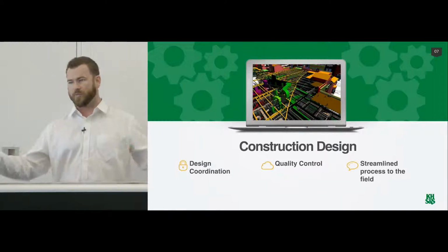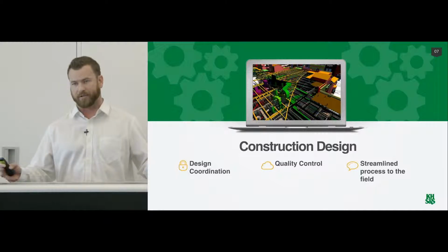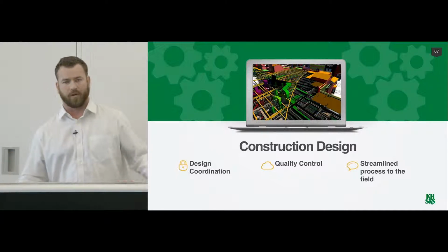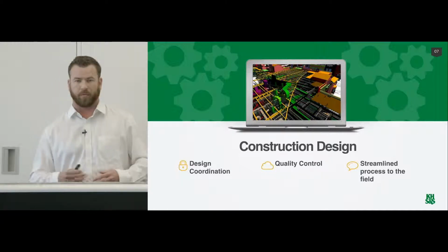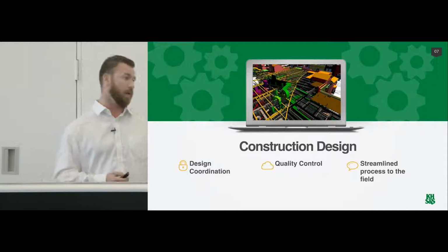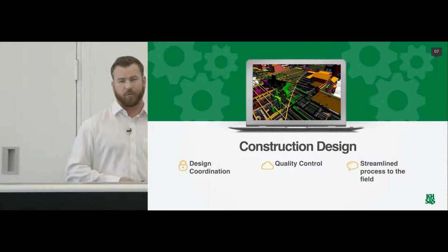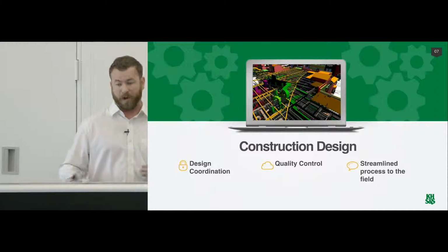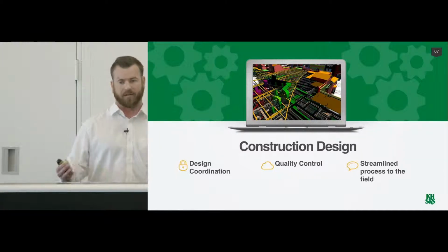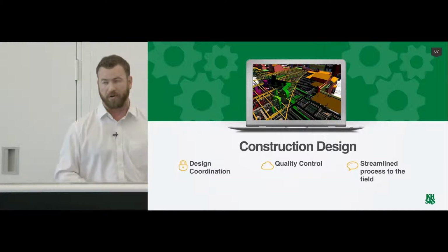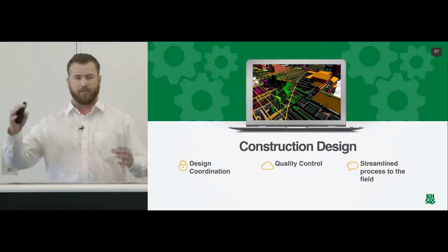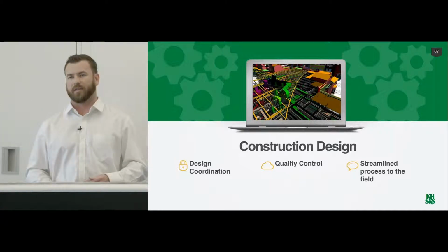So again, this is probably not new information. Everybody knows clash detection, BIM, building information modeling. Another step that we do with that process is early on in the construction, like pre-con, we're involved in the pre-con meetings saying, hey, we think it could be framed better, more efficiently here, there. This is a better detail. So we're looking at better ways to frame, perhaps that aren't really captured in the design. We know the architect's concept is there. We try and make that a reality. So the full process started out: we design it, we model it, and then we clash detect it, then we build it, right?